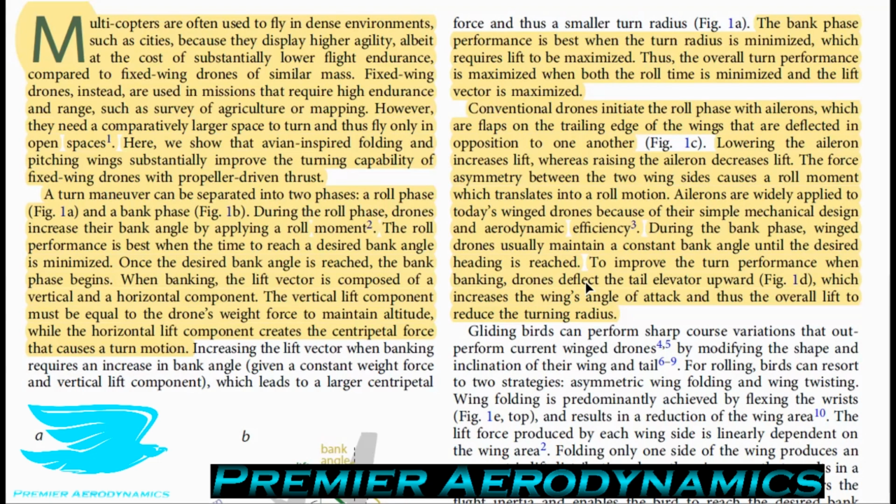So the ones inboard, closest to the windows, are mainly used to increase the lift of the wings in a symmetrical fashion. So both the flaps on the left and right wings will be deployed at the same angle typically. But then the ones further out near the wing tips are called ailerons, and these will be pitched at different angles of attack to change the resulting lift of each wing individually.